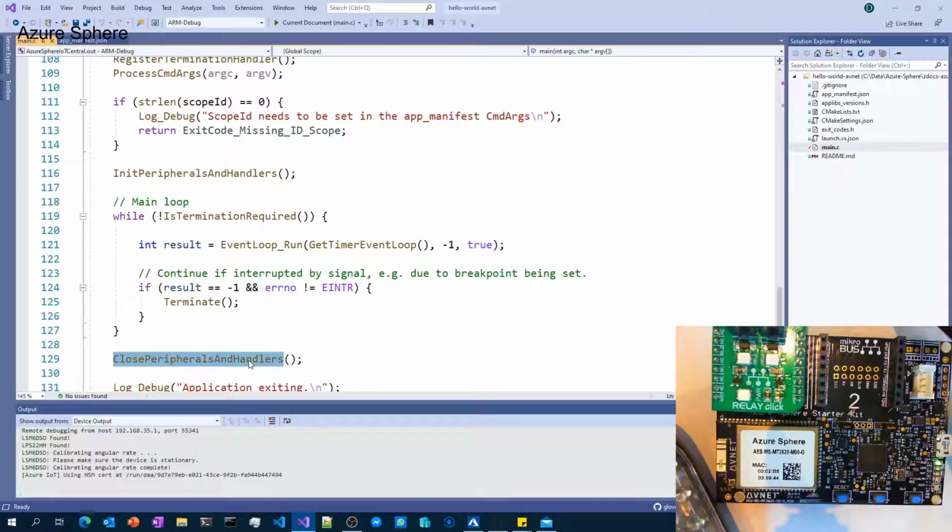So if you could look at the top of the screen, what I'm going to do now is set the build configuration. So I'm going to select ARM debug, and then I need to select the startup item. The startup item is GDB debugger HL core. You remember HL stands for high level. It's the high level core on the Azure Sphere, which is the Cortex A7 core.